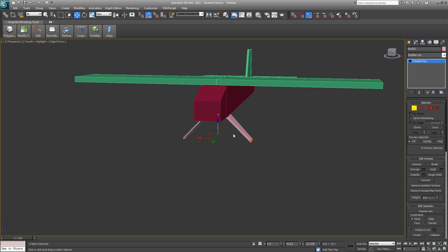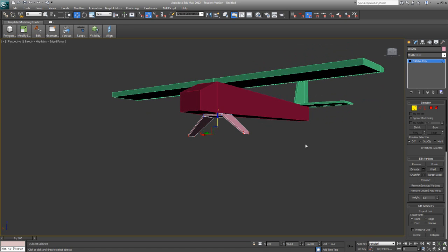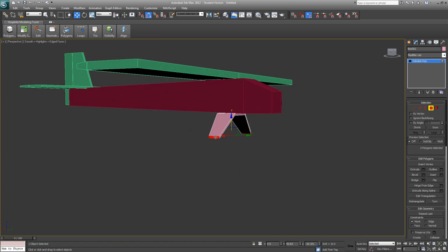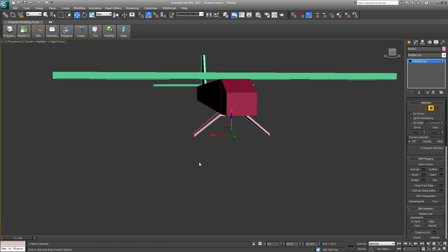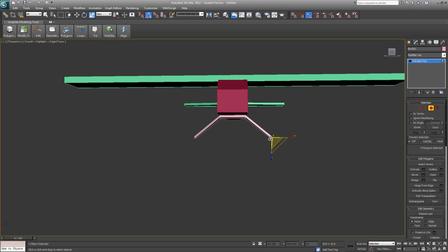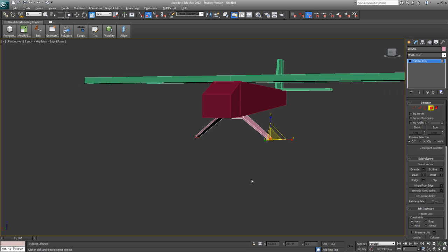Alright, now that I got that, I know that I want to move these back up. Nice. Now I'm going to hit Control and go back to Polygon. Okay, and yeah, I can see why they didn't work, because all of these faces are touching those verts, so we'll just reselect them. Okay, so I'm going to go up here to Scale, and I want to turn these faces so they're 40 to 45 degrees, like a picture frame.